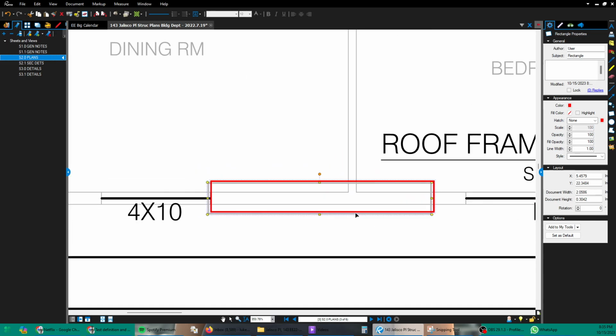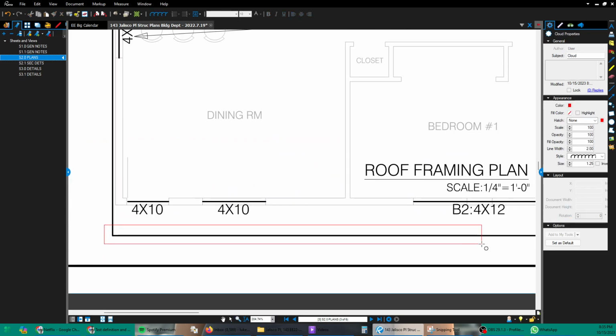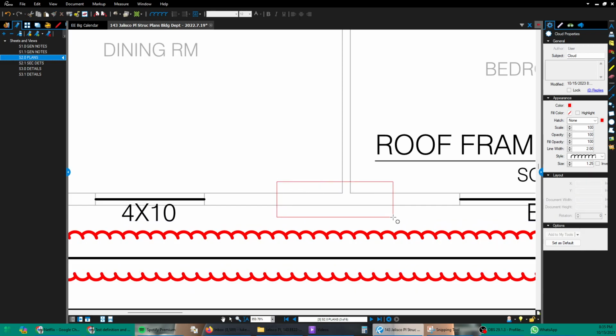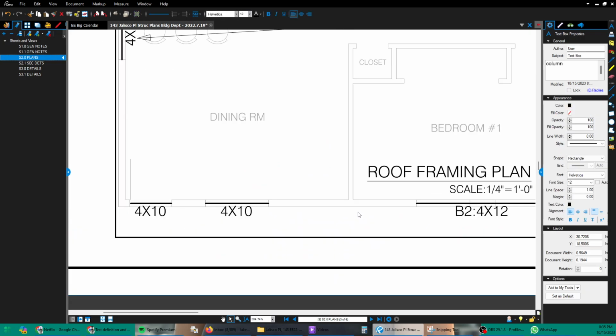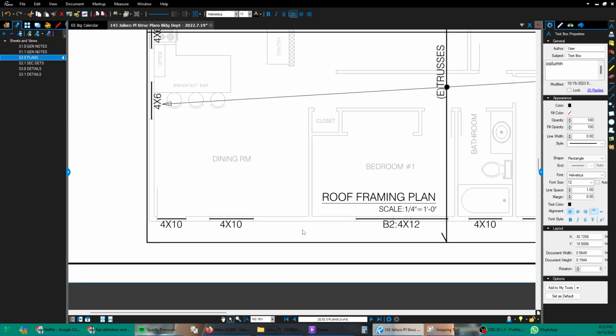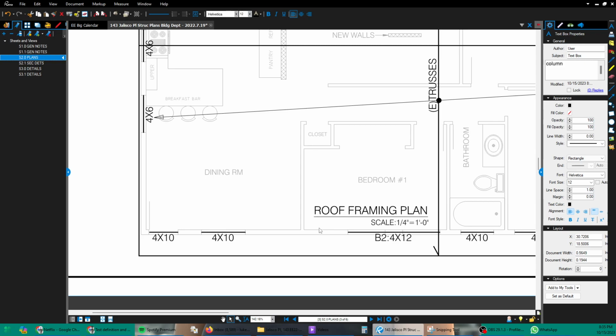So this is the exterior wall in here, under there, and notice that here is the edge of the roof. The edge of the roof is extending beyond the exterior wall. That is called an eave. The house roof extends beyond the exterior wall, and the reason for that is that when it rains, the roof will shed the rain off either into a gutter, or the water will fall off the roof away from the walls. You won't have water just running down the face of the wall, as would happen if the roof edge ended right at the face of the wall.